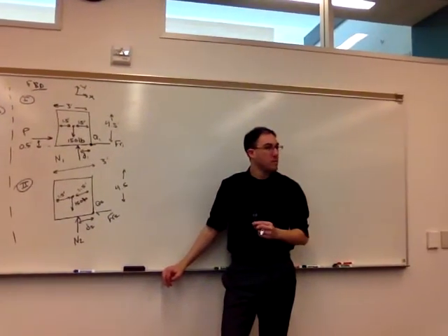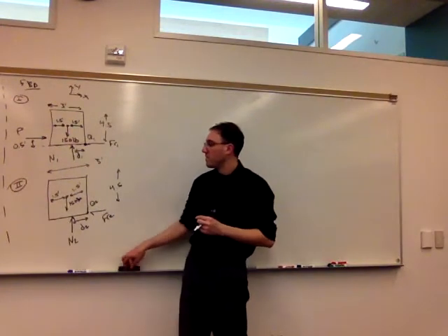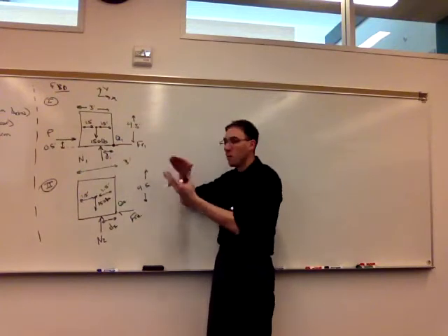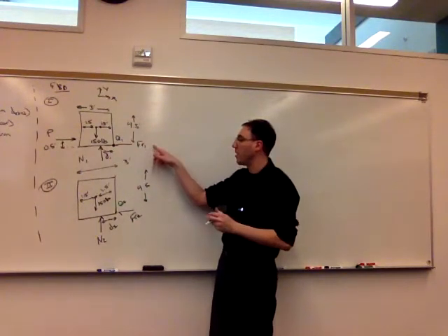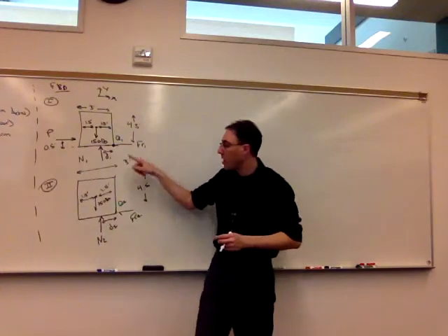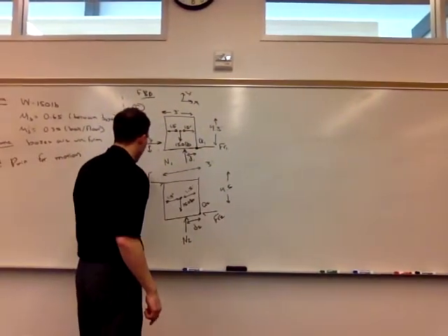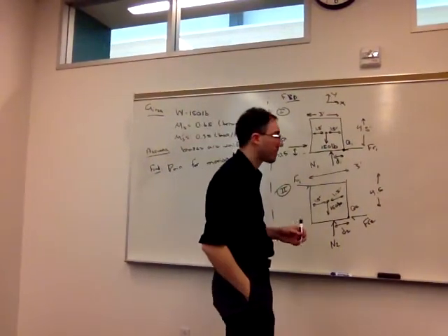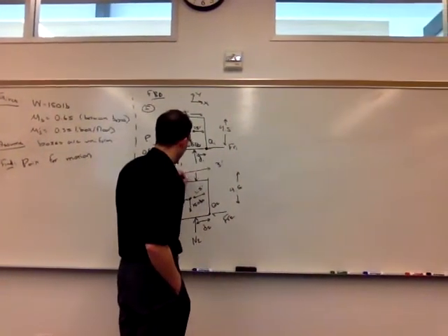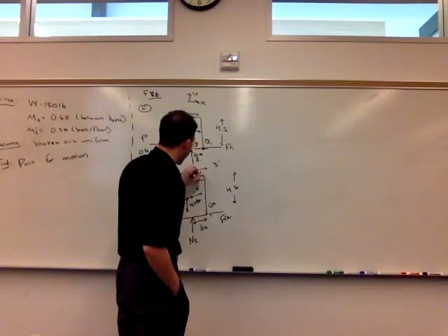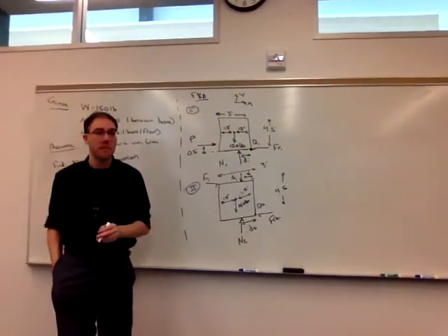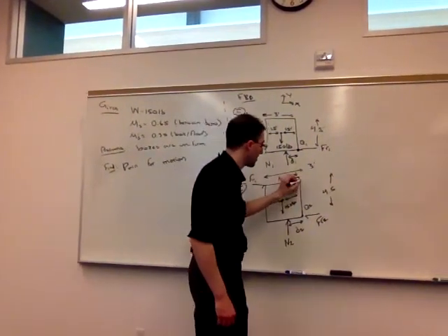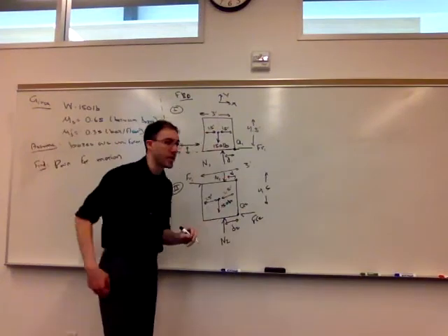We also have the first frictional force on this one too, except acting in opposite direction. Correct. So just like we saw in frames and machines, we separated those surfaces, so we exposed in the drawings this FR1. We have to have that equal and opposite force, FR1, in this picture. Normal force N1 on the top, distance D1 from the right side. Right, so same idea, equal and opposite forces at that equal and opposite location. So N1 down in this picture, D1 also measured from this top section here.